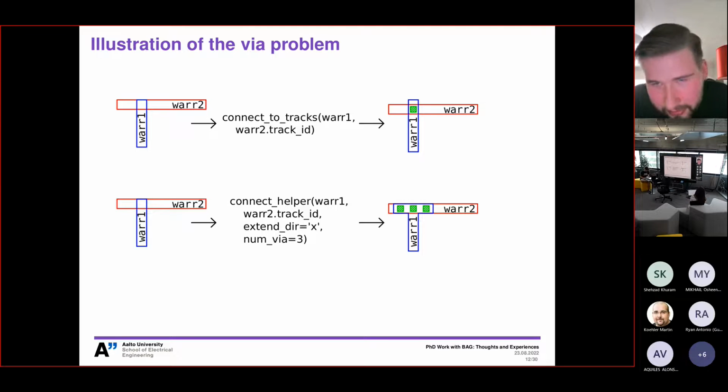On the other hand, this creates some problems, as you may imagine. If you have wires on the same layer as wire 1, right near this wire array, and you try to route over wire array 2, then you will short out the wires, and you have to manually take care not to do that.